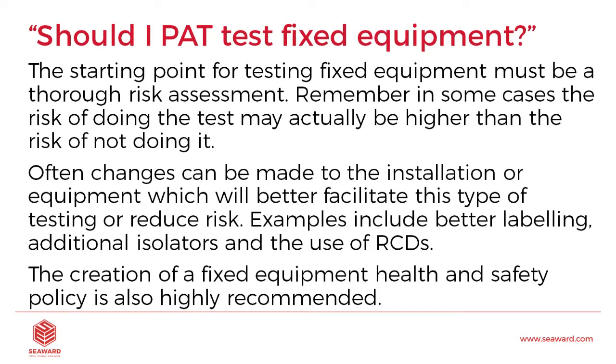The starting point for testing fixed equipment must be a thorough risk assessment. So remember, in some cases, the risk of doing the test may actually be higher than the risk of not doing it. So again, you've got to think of working at heights, have people got access to it? Can they physically be hurt by a fixed appliance? Is it out of reach?